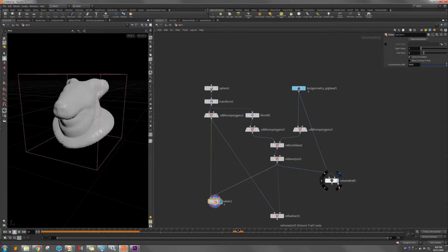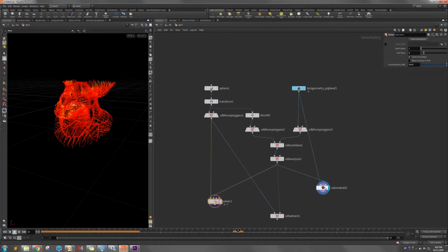So here, some people ask what the difference is between using fog density, fog VDB, and distance VDB. Actually, you can use either fog or distance to achieve what you want. The difference is that when you work with the distance VDB and calculate the vector from the gradient, they always point to the surface. In that case, it will be from the interior to the surface of the pig head, because the distance VDB in the surface attribute defines the distance to the surface. So it's not the same as the fog VDB, the density.